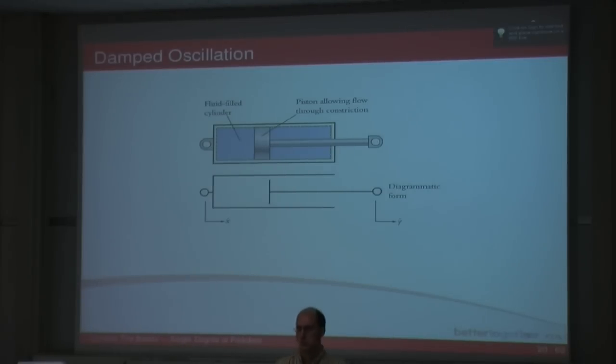The other type is called pressure damping, and that varies depending upon the velocity squared. An example of pressure damping would be aerodynamic drag. That's a damping that depends upon velocity squared. As v goes up, the frictional force associated with aerodynamic drag will go up by v squared. It's why travelling at 80 miles an hour uses quite a lot more fuel than travelling at 70 miles an hour, despite the fact you're only travelling 12 or 13% faster.